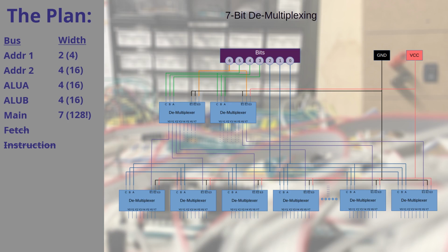Now, once again, I'm not planning on using all those 128 different signal lines. I am going to design the PCB to be able to handle it, and I simply won't populate some of the ICs that I don't need. So that then gives me the plan. What's the other caveat, Adam?